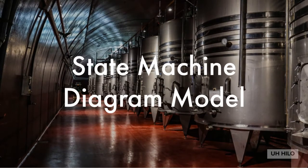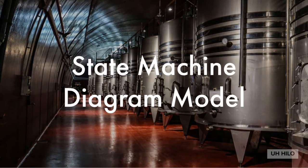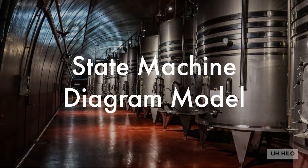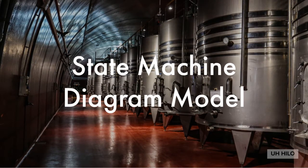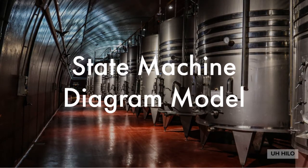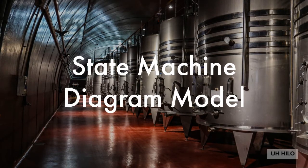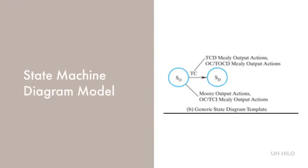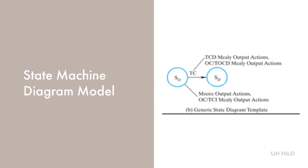We'll need input conditions, output actions, and transitions for our model. An input condition as an expression is either equal to 0 or 1. An input condition on a transition arc is called a transition condition, or TC, and causes a transition to occur if it is equal to 1. An input condition that, if equal to 1, causes an output action to occur is called an output condition, or OC. For our new model, we permit output conditions to appear on the state, not just on transitions. We also permit output conditions that depend on transition conditions to appear on the arcs. This provides modeling flexibility in the formulation of corresponding state tables and HDL descriptions.